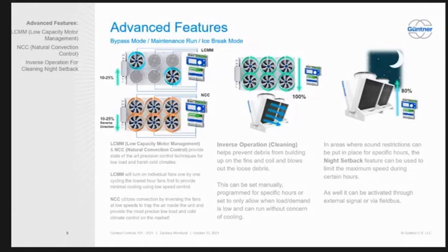Back when they first started doing a lot of analog output control, they did not have it set up that way. So if you lost your analog output, you were looking for some kind of Hail Mary to get those fans running, just to get the rack back up and running. So what we're talking about is making sure it is inverted, so if we do lose the analog output, we still have some fans rotating.